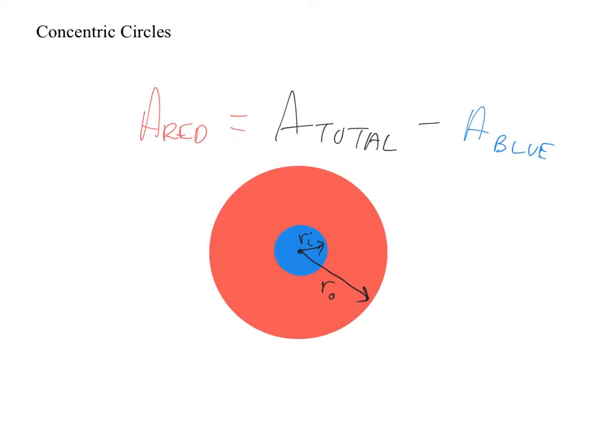What else about concentric circles do I want to know? There's a term called wall thickness. How would you figure out the wall thickness with concentric circles? If this were an object and there was an outer wall and the inner part, how would you figure out the wall thickness? What would you do? If the circle is inside of the wall, find the area of the whole circle first and then subtract that from the area. Close. They're thinking area. That's what you just did up top. So wall thickness, though, is not area. It's not a measurement of area. It's a linear measurement.